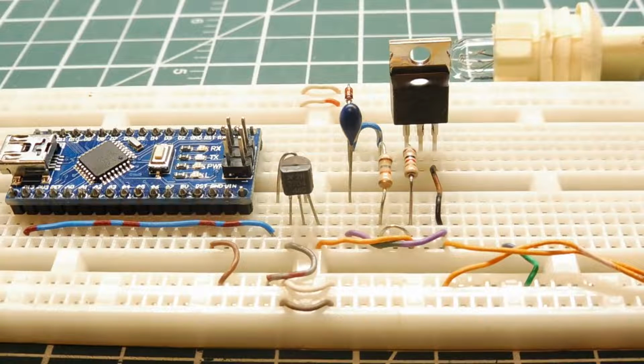Now normally if you want to use a MOSFET as a high-side switcher, you would use a P-channel MOSFET. It makes it a lot easier. But if you run into the problem where the drain to source resistance is just too high, this is one solution. Also, if you want to turn on your load constantly, you could build a charge pump circuitry for 24 volts and feed that into the gate of the MOSFET. But I just wanted to come up with a low part solution. So I made this video to give you guys an introduction to how bootstrap circuits work.